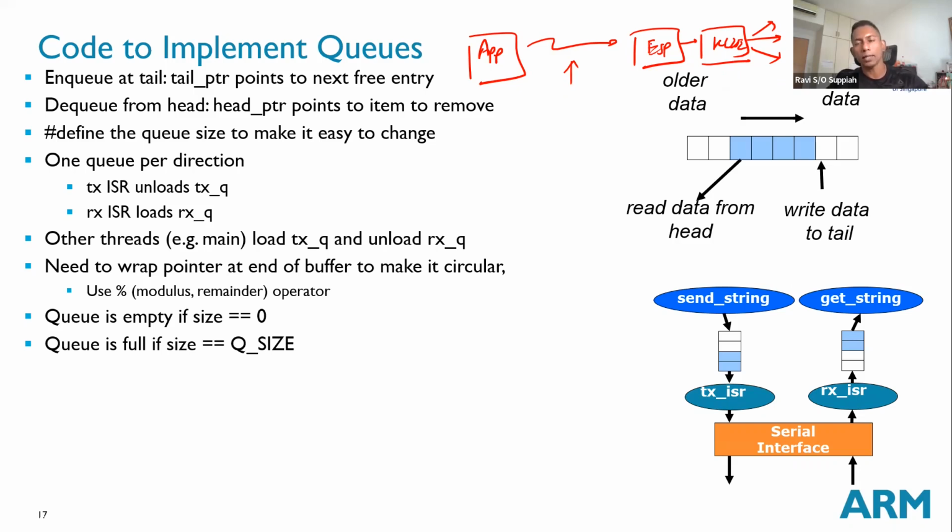So if I send a command to move the motor, I expect the robot to respond by moving the motor immediately. It's not that I say move the motor about 2 minutes later. I'm not going to send a command like that. Whatever command I send, I expect the response to be immediate. So in our scenario, there is no need to buffer any data. You don't need to create a buffer and then process the data slowly. You don't have time for that. The moment an incoming packet is received, you straight away decode and process it. There is no time to waste.